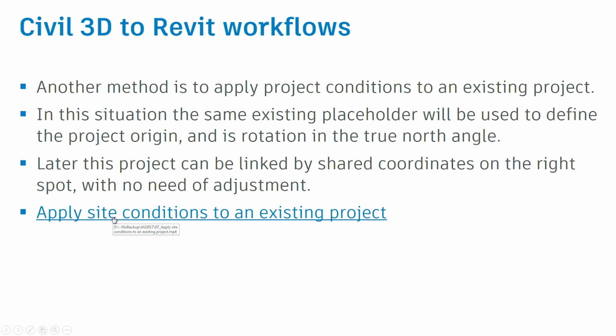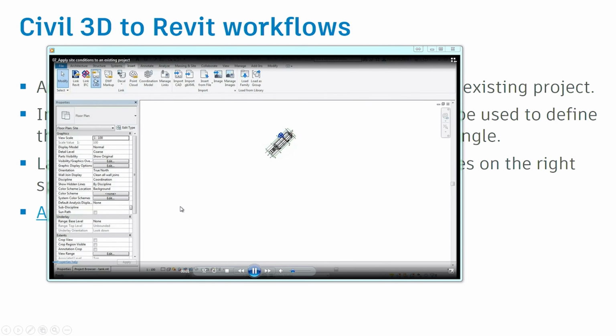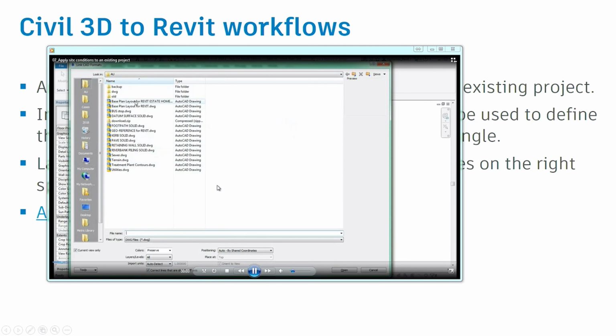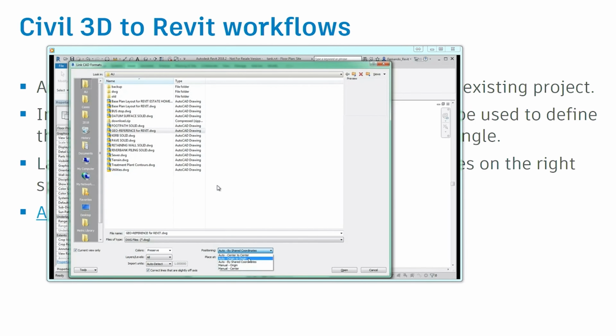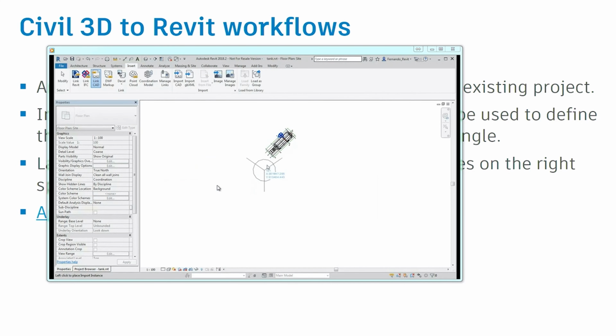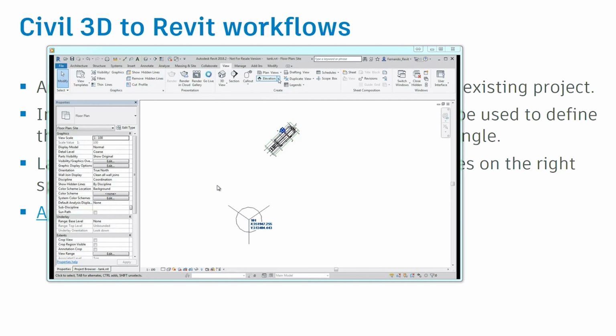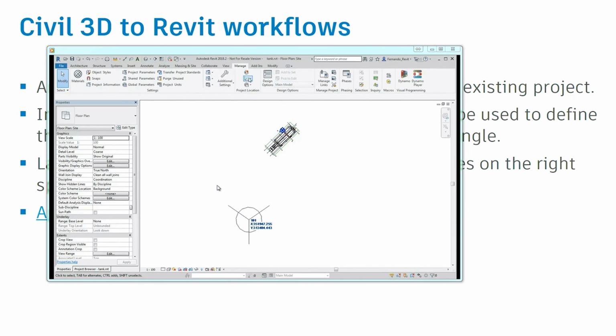And this is a different way, where I have a more complex model where I need to establish rotation. That's sometimes the other problem, how we rotate the model correctly. So on this model, I'm going to grab the small placeholder we have. I'm not establishing the position yet, only starting to acquire the coordinate system. That's what we're going to do. And then apply the rotation to north. For that, you need to be in Project North, in True North. Let's see. When we do True North, it rotates there. We change these.